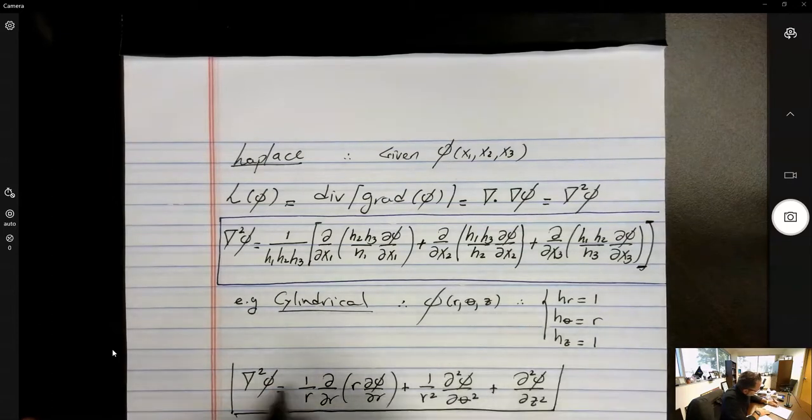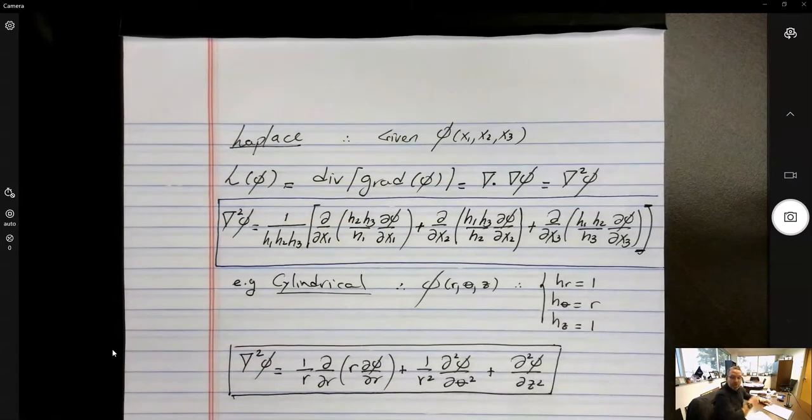That's sort of simple. So if I, for example, have a differential equation like the equation of heat conduction in homogeneous media, which we already derived and explained, that equation has the Laplace in it, because through conservation of energy we figure out that would be the differential equation that governs heat conduction. Then if we want to express that equation in cylindrical coordinates, this is the differential equation that we'll need to solve. Not just the second derivative with respect to r squared. It has to have those scale factors embedded in.